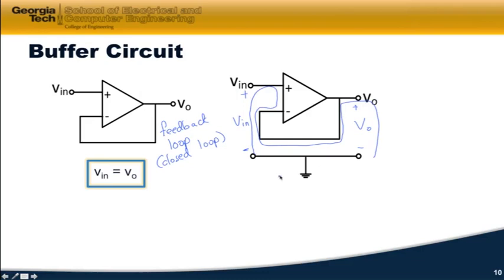The way I do a KVL is I will go to here. When I see a negative sign on an element, I add in a minus voltage and going around. Now, actually, when I go from here to here, I'm gaining potential, and I come around here, I'm losing potential. But just for my sake and a lot of students' sake, it's just easier to use the convention.